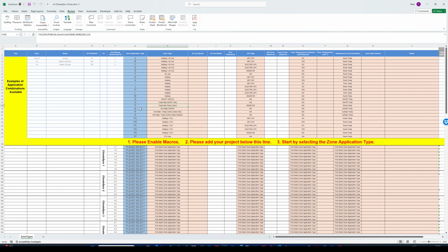Type Q, R, and S, all three are hot water control, where type Q is hot water on-off only, where we will only activate the relay, but we will not be temperature controlled. Just as a scheduled timer, we will use it, or just to switch on and off the hot water.